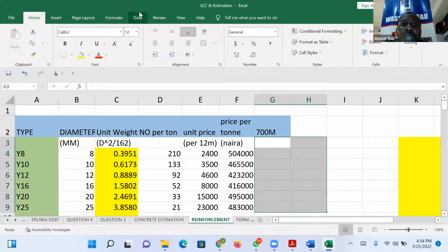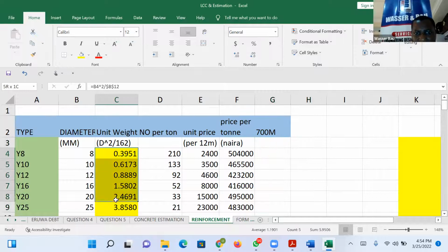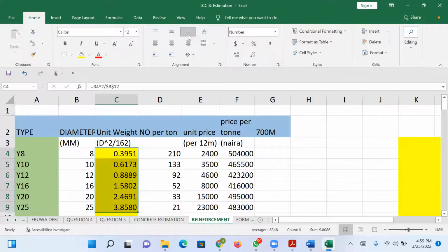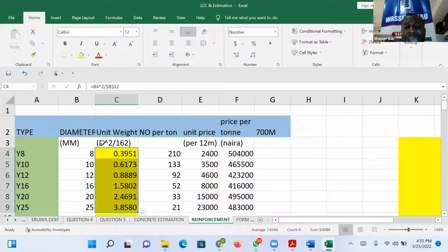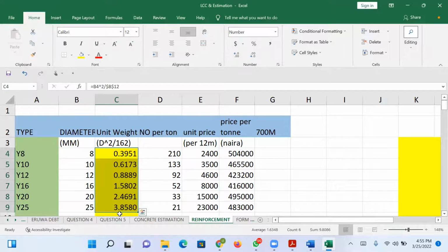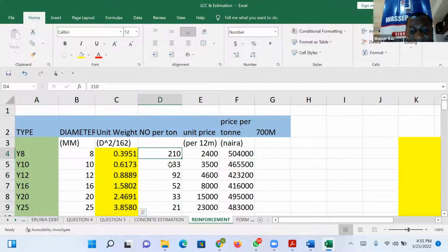So what I want us to do now is go through some of these unit weights. Can we quickly go through them online, just like we did? Can you corroborate this unit weight? Then we'll move forward. I want to give you 2 minutes. Go to Google now, just check unit weight of concrete. And then for each of them, try to do the density, diameter square over 162. Make sure you are getting this, so that it will become something in your system that you don't need to Google again. And also confirm whether this is the length that gives this.